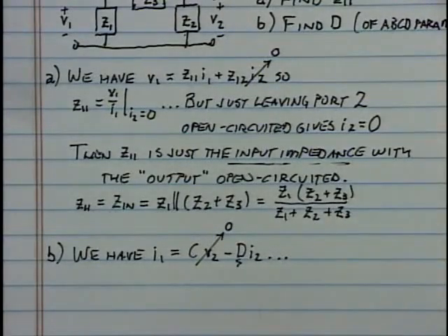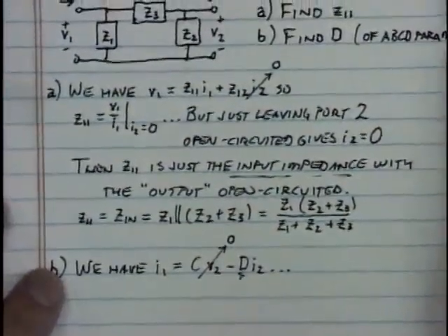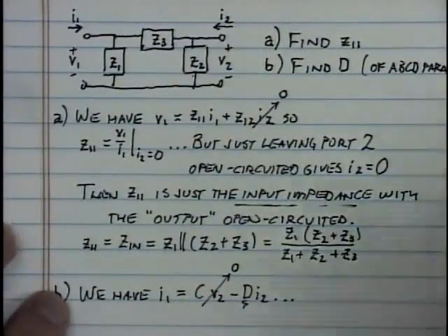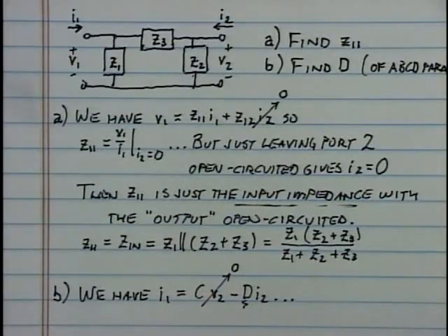How would we get V2 equal to 0 in the original circuit? Now this is the calculation we've got to think about, or this is the measurement we have to perform. We've got to find the ratio of currents at the two ports when V2 is equal to 0. How would we make V2 equal to 0? I can think of one very simple addition to make to this circuit that would enforce V2 being equal to 0 always.